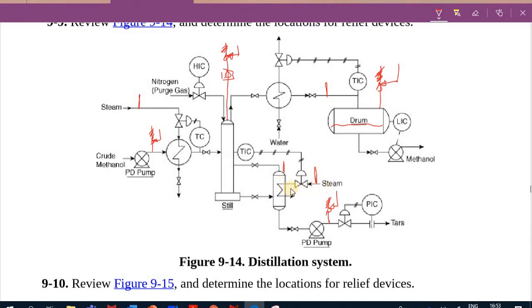Sometimes it's important to know that, because we also want to protect the pipe, which is part of this whole system. What about if my inerting, or the purging that I'm doing with nitrogen here, also does not work? That is something else where I could reach flammability limits here, and getting to flammability limits could also be dangerous.